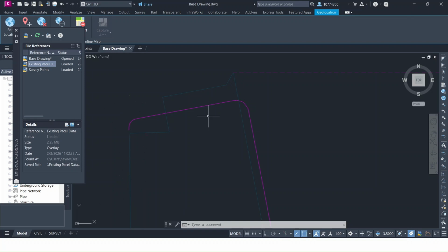So let's say you freeze it and you save the drawing, forget about the project, or you come back to it later, and you're like, man, why isn't this layer working, why won't this turn on, why can't I see it? And then you're like, oh wait, I froze it. When you freeze it, you're freezing one particular layer, and it will not display until it is unfrozen.